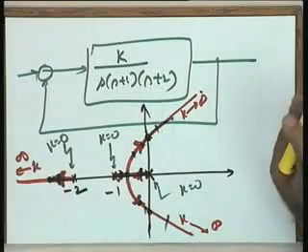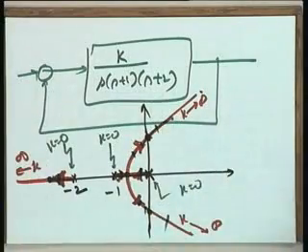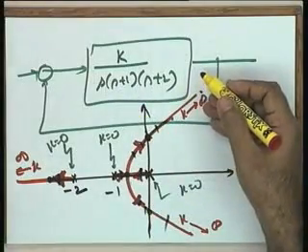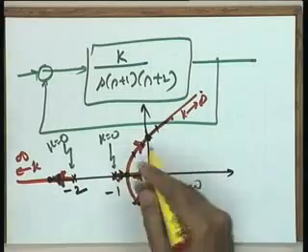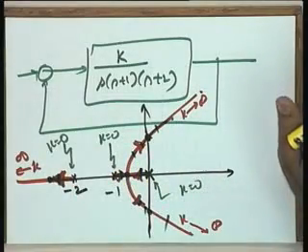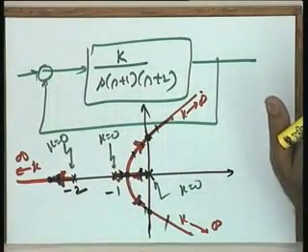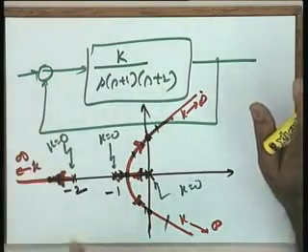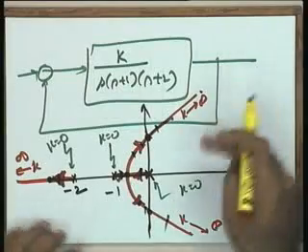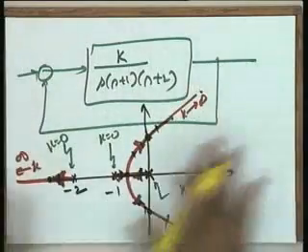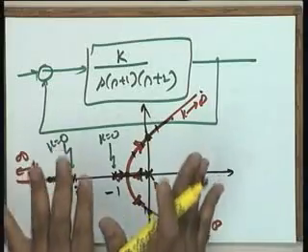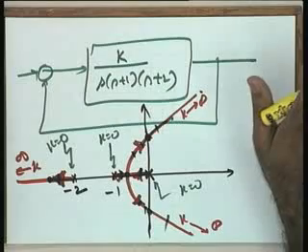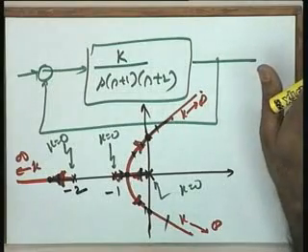Okay, you can at this point say, what is a root locus method after all? If I have the characteristic equation, I can sit at the computer terminal and get the poles for any value of k I am interested in. My argument is the same as I gave you in connection with the Routh stability criterion. There only numerical values will be available to you. You will definitely need this type of sketch to see how the parameter is going to affect the closed loop poles. So, those numerical values are also required to be plotted.